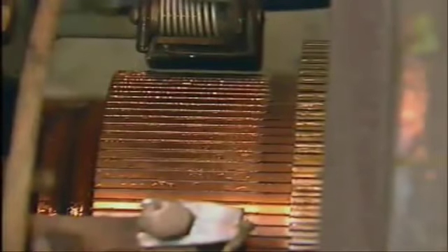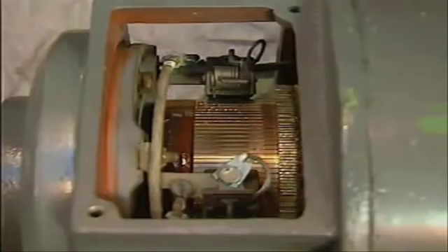A commutator in good condition has a smooth, highly polished surface. Commutators generate a film over their surface that aids the current flow from the brushes to the commutator. The color of this film ranges from a light brown to a chocolate brown when the commutator is in good condition. Care must be taken to avoid removing this film as the commutator is being cleaned. If the film is removed, commutator efficiency will decrease and the brushes may wear more rapidly.